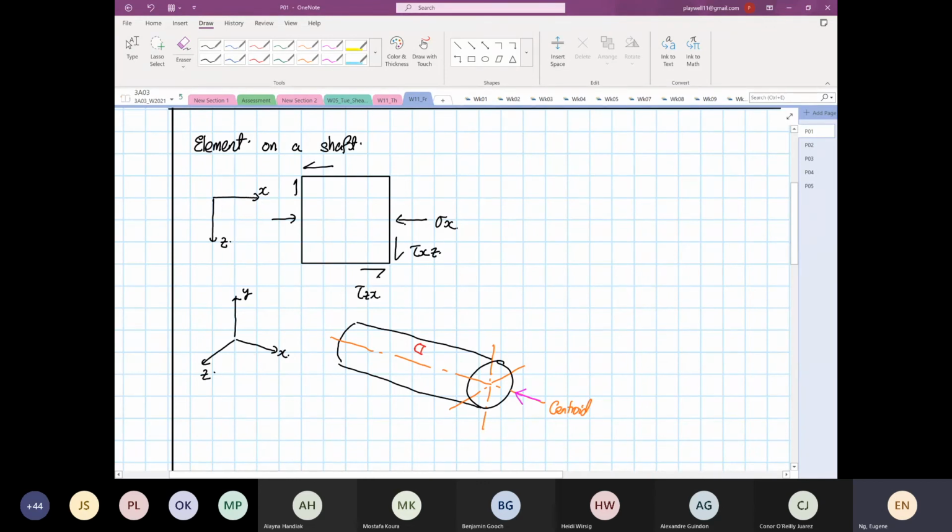This is our axial load. Then we can have a point load coming vertically down, and that is our Py. And we can have another force coming in this way, that is our Pz. And then to make matters worse, or in reality, we will have a torsion. So this will be torque in the x direction.